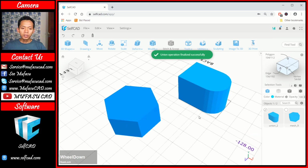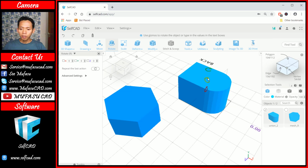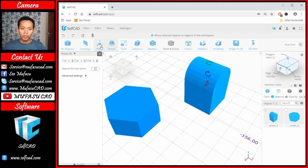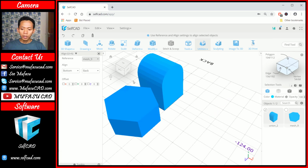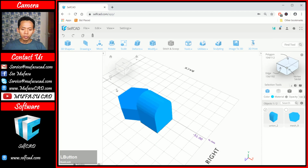Okay. I will use the rotate command to rotate these 3D models. You can click here, rotate. We rotate in the blue axis. Okay, I will rotate 270 degrees, and we can move this object into this object. You can use the align command. I will change the guide here to mesh. Okay, now we can change it to right. You can click here and change to right. You can click close.